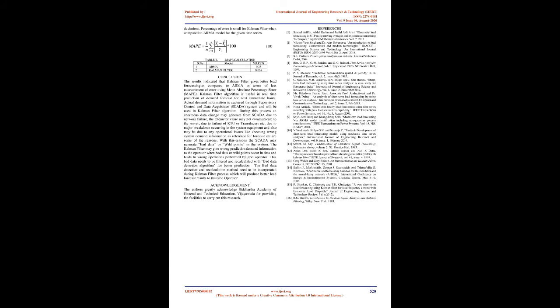A. ARMA. Short-term load forecasting using the ARMA technique was presented. From the ACF and PACF plots given in Fig. 3, the order for the AR model is 2 and the MA model is 1, and the load demand was forecasted using ARMA(2,1), and the results are presented in Fig. 5, which is a zoomed form of Fig. 4. The blue line is the original data and the red line indicates the forecasted data, where it is observed that the load forecasting has been estimated accurately with some measurement error.